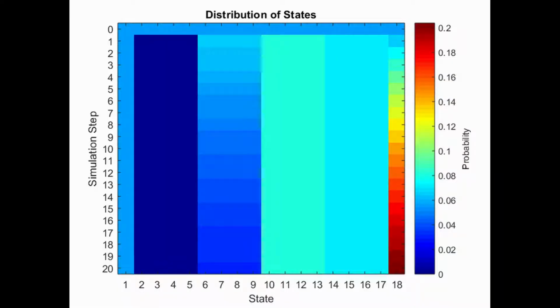The MATLAB output for the two series, two parallel configuration is as shown. We've accomplished 2 things with this. So we've increased the amount of time that it takes before that failure rate gets relatively high, and then the overall failure rate is just not as high as with either the two series or the two parallel or just a single capacitor configuration. And we've been actually able to reduce that by 70%.